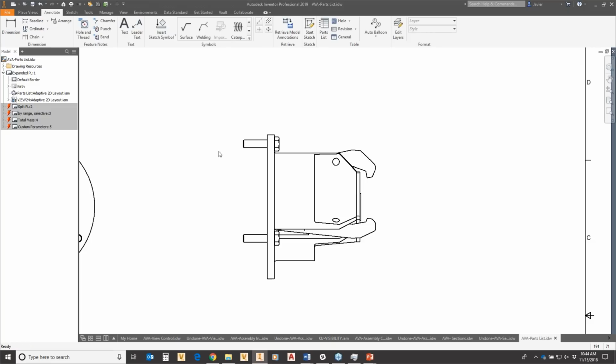So when I go to the Annotate tab, a lot of people do this. They just balloon things one at a time. And so when you do this by default, it does this. You pick, right, and that's all you want to do. You want to be done with this, but it thinks you want more segments. And so I don't know anybody who balloons like this. So it requires you to right-click and choose Continue, and then you could start to continue ballooning, right-click, Continue.